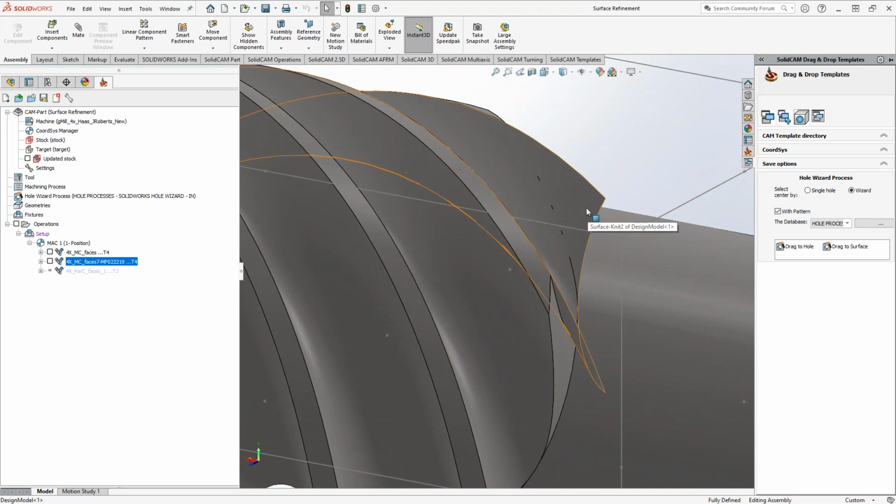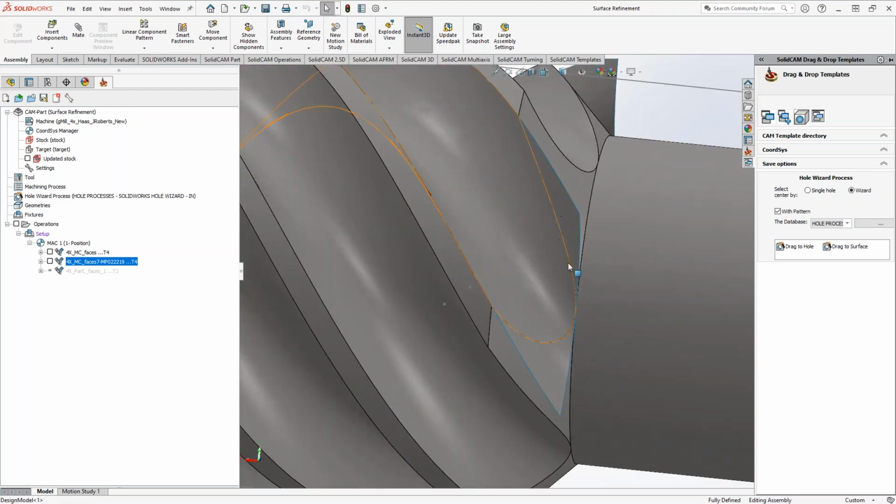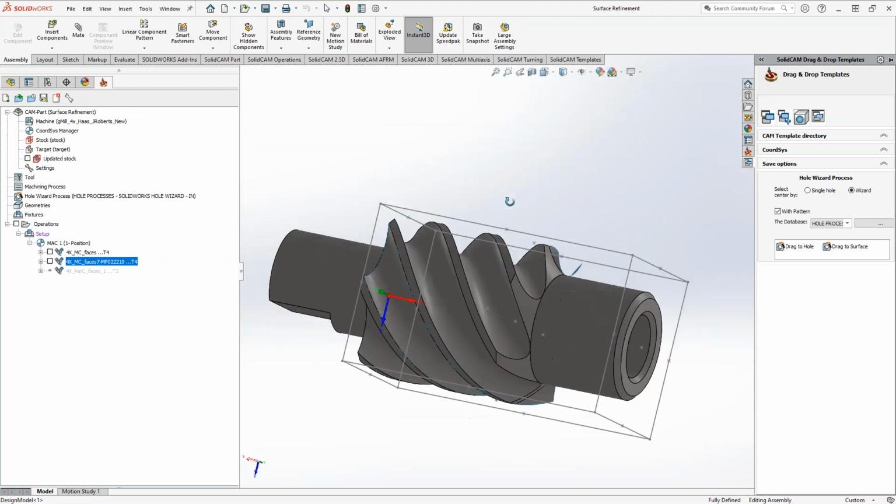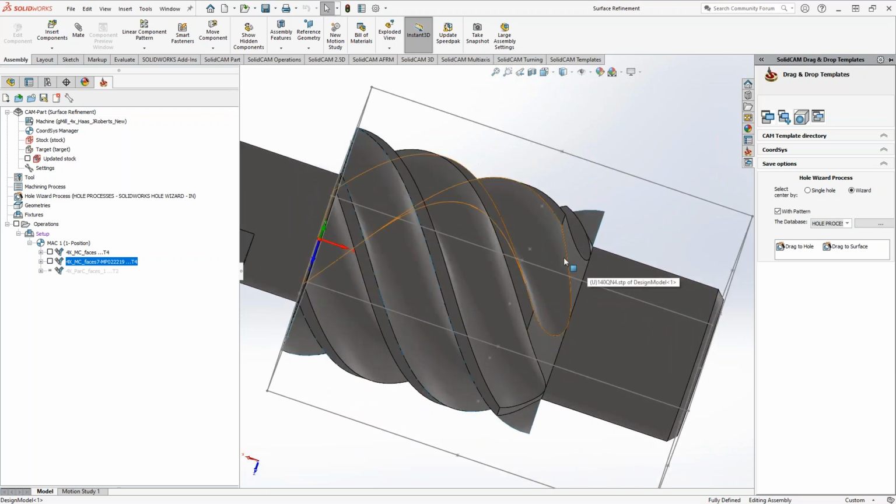Well, outside of actually doing surfacing inside SolidWorks, which is always a possibility, especially for 5-axis, you can do your lofted curves, your sweep curves. You can try trimming. You can even use a split line here if you wanted to. Let's get a more representative edge here. If you wanted to just do a split line to get that nice cross section so you can get that edge, that'll help you as well.